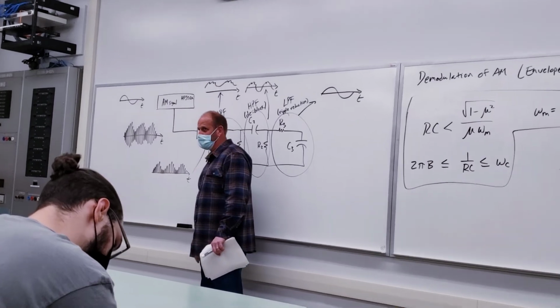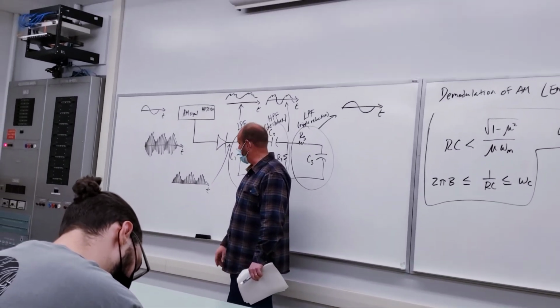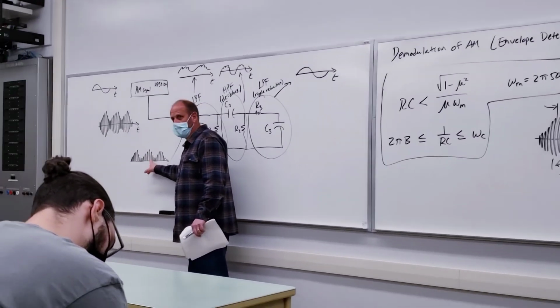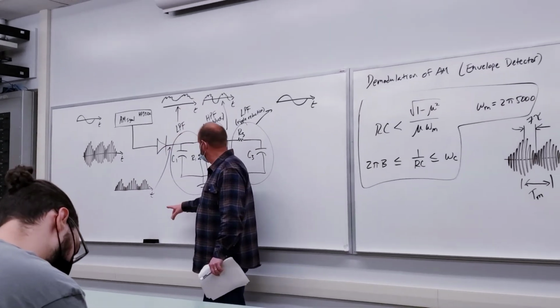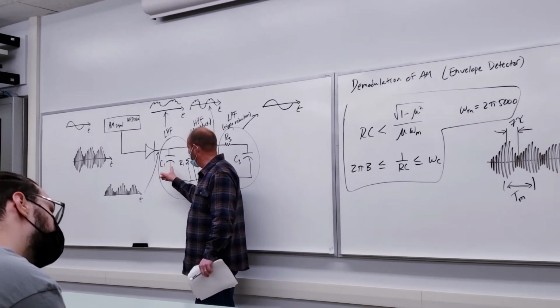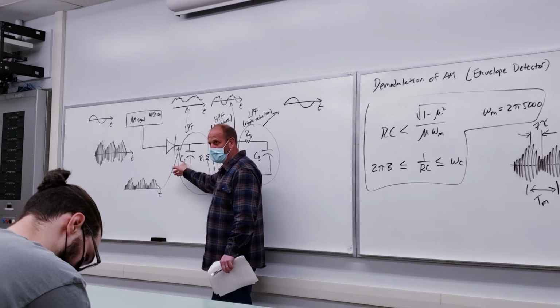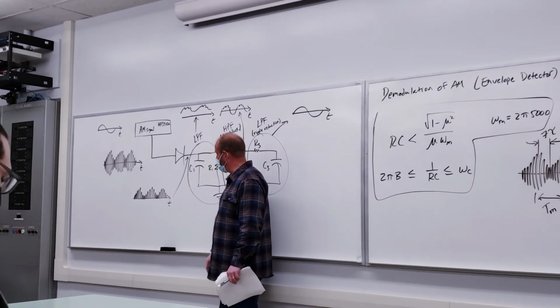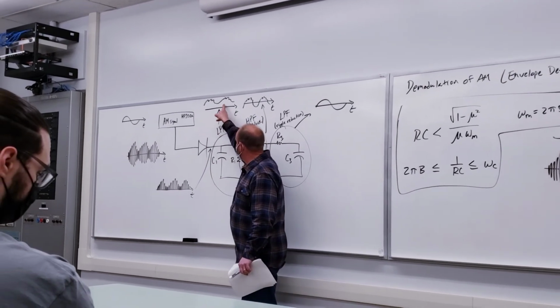It's too fast a circuit. It's not sluggish enough. It's following the carrier. So what do you do? Turn up a larger value for R or for C. Turn it up a little bit, and you should start getting something like this.